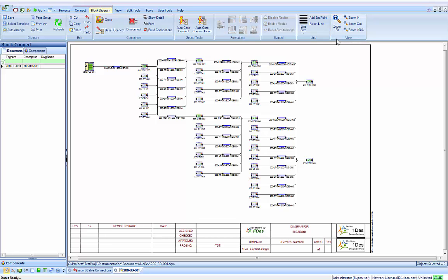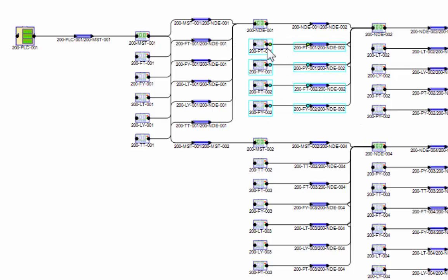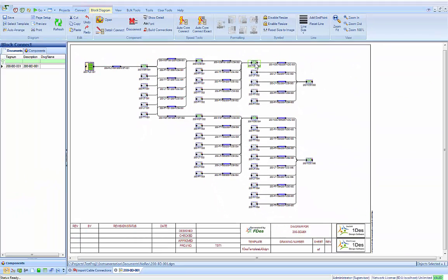As I've mentioned, there is a specific order in which the components should be connected. A card panel can connect to a master panel. A master panel can connect to another master panel and daisy chain like that. A master panel can connect to its first node. That first node can then connect to the next node and daisy chain. And the instruments that are connected to that node then will connect from the instrument to the node. If the order for this is swapped around, there is no guarantee that the Net Layout document type will function correctly.